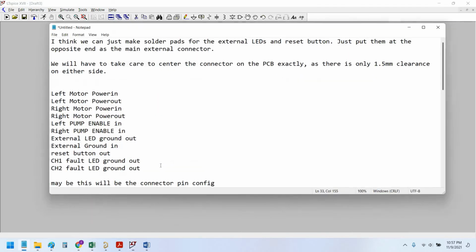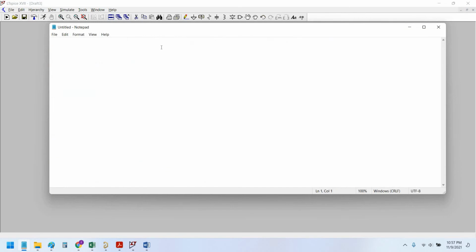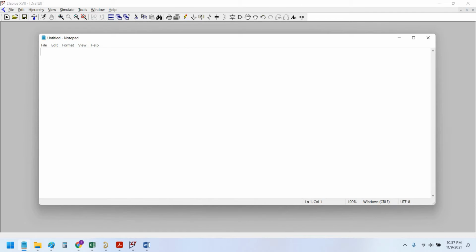So for the 20 Hz, F equal to 20 Hz is equal to, the formula is 1 upon 2 pi RC. Let us assume R equals 10 kilo ohm. So we can easily calculate C equals 1 upon 2 pi into 10k into 20.